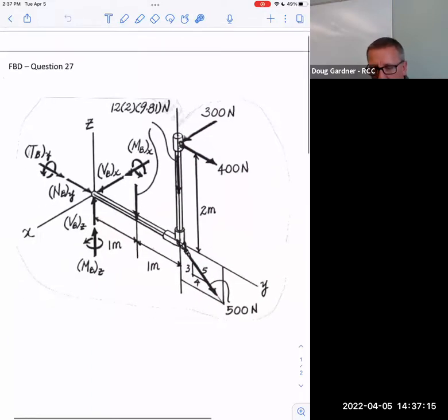And then the other reason I included this is in your problem, it says that it had 12 kilograms right here, but remember, kilogram is not a force. So you have to take 12 times 9.81. And that's the center of mass of that rod. And it's 2 meters long. So it's 12 kilograms per meter. That's how much the bar weighs. And that part of the bar is 2 meters long. So it's 12 kilograms per meter times 2 meters times gravity. And now that's actually newtons. And that N right there is newtons, not normal force.